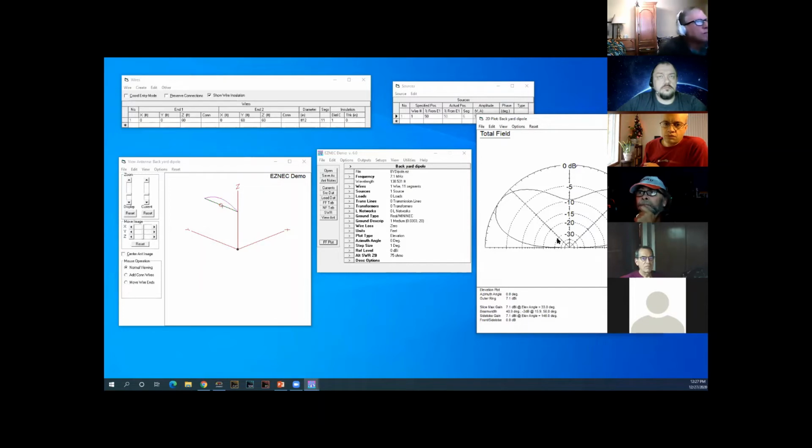The elevation angle here is determined by an interference pattern from the dipole and reflections off the ground. You can kind of play with this. You can change your antenna height. Let's just do that right now. I'm going to put this up at, say, 300 feet. You just spent a lot of money, and Lavelle is going to help you put up your 300-foot tower. Let's do that.